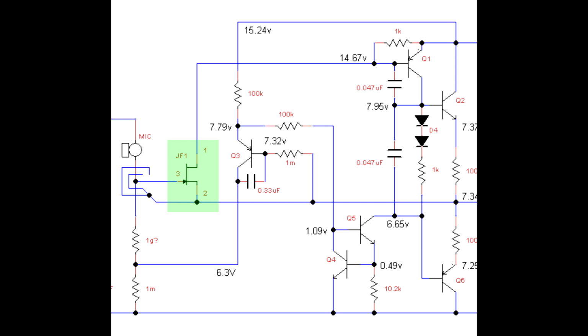So they convert voltage into current. So the JFET transistor will now be wiggling and letting through a little bit more current or a little bit less current. They're almost like a variable resistor. And that wiggle in current then wiggles the base current through the PNP transistor, and that then gets fed to the output section. So that's the way the signal gets through.